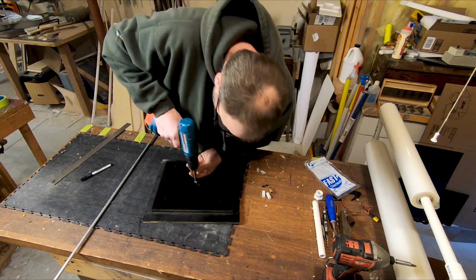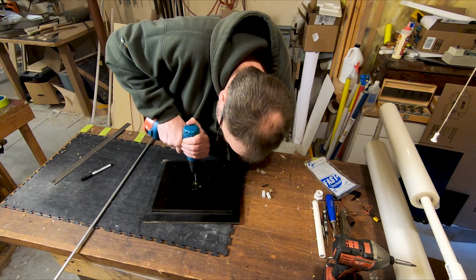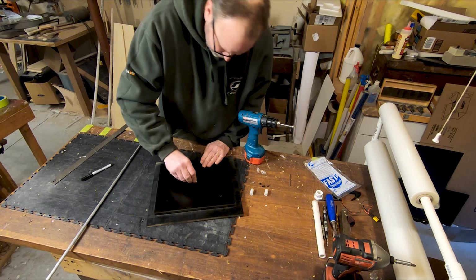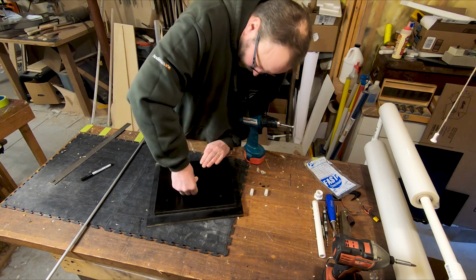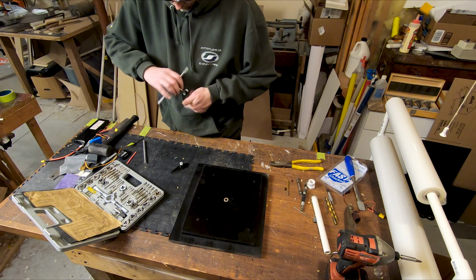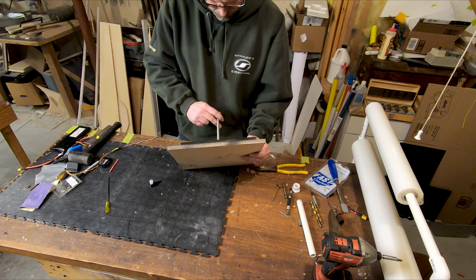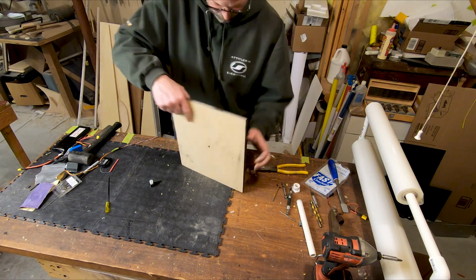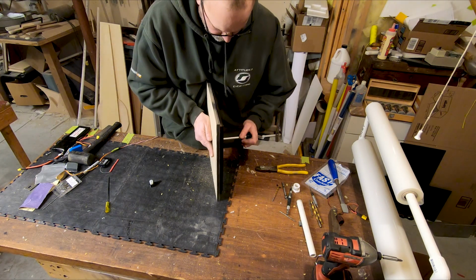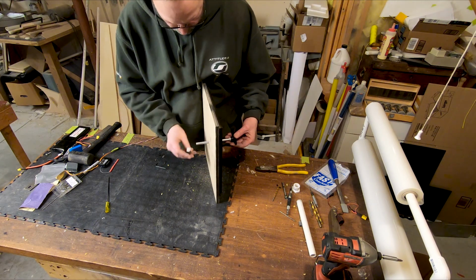The support strut is made out of 3/8 inch aluminum rod that goes through the panel into a bronze bushing. I printed the control horn for the outside and the airfoil support bracket for the inside. I drilled and tapped the side of both so I could add a set screw. This makes it easy to adjust and mount the airfoils.